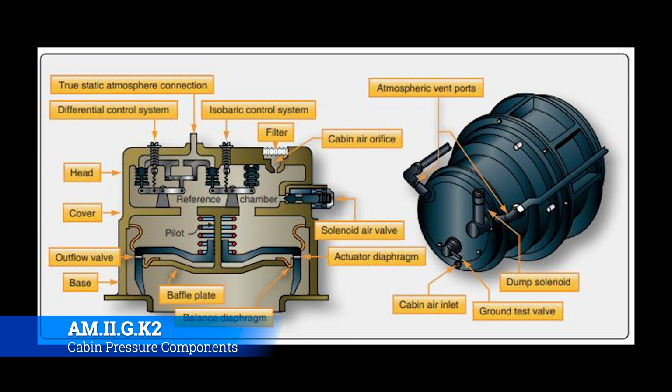I will tell you, these things do get messed up from time to time, and you end up having to replace them. And then what you'll do is you'll just replace the valve body and reconnect everything, and then you'll do a low blow test, and it's not really that big of a deal to have to work on them. But this is kind of like the meat and potatoes. Granted, your bleed air and all that good stuff is what pressurizes the aircraft actually, but the outflow valve really is kind of the center of gravity for that entire system.